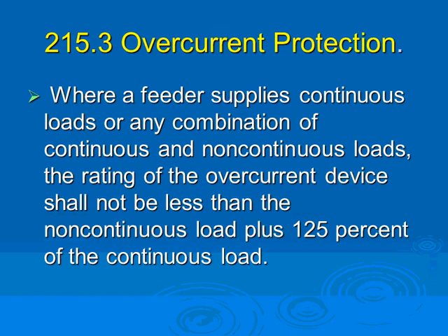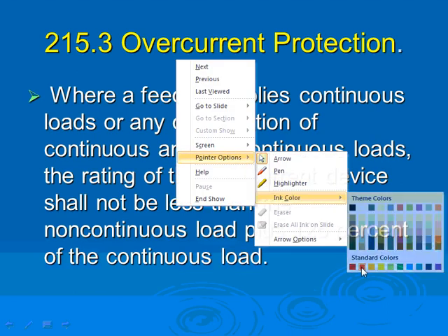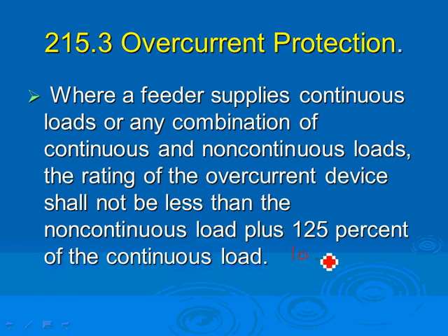Any comments, guys, about sizing them? A good simple example: say I have a 100 amp load that is non-continuous, and another 100 amp continuous, and I need to size the service for it. You take the first 100, add to it 1.25 multiplied by the second 100. That's the 25 extra on it, and if I did my math right, your service will be 225 amps. This could be a branch circuit, a feeder, or a service conductor.